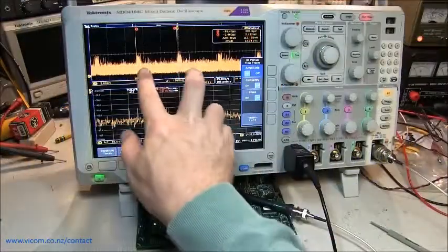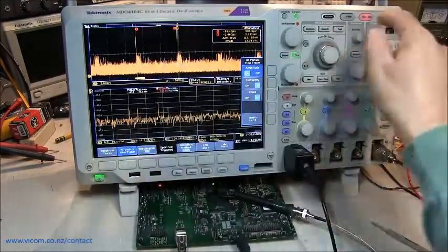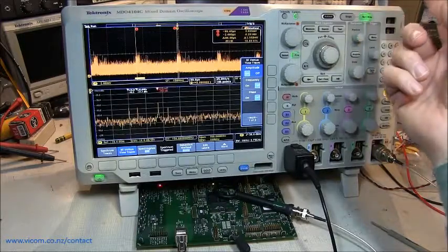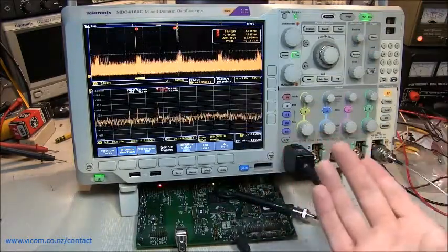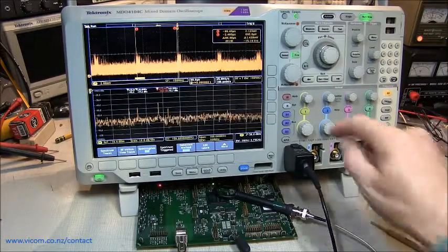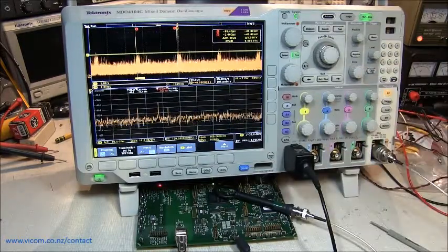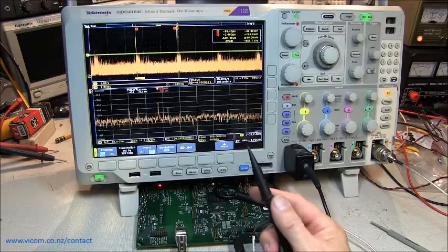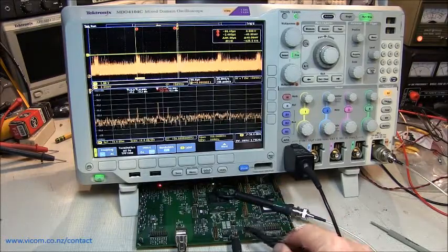If the time domain nature of the signal is not enough to help you identify it, we can use the fact that we're triggering on the signal itself to help us identify a coincident signal. With the scope still triggering on the RF signal, let's add channel 1 and start probing around on the board with our oscilloscope probe to look for signals that are coincident with that event.